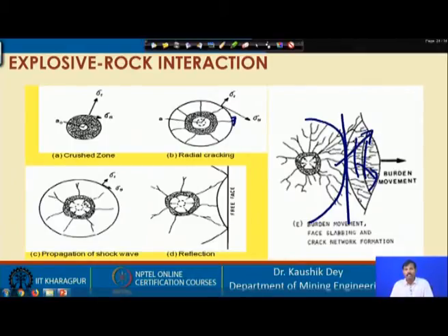The reason is that the gas produced is of limited quantity and limited pressure. If there is a huge solid rock mass in front of the gas produced from the explosive detonation, it cannot throw that rock.